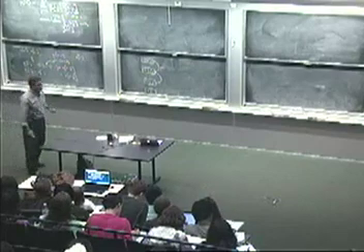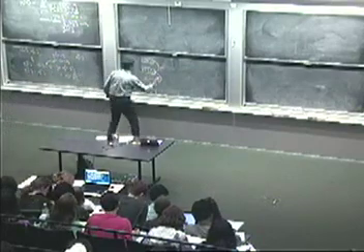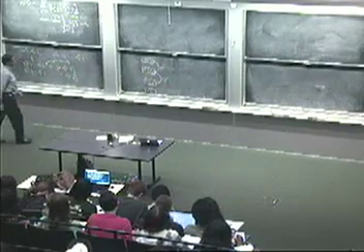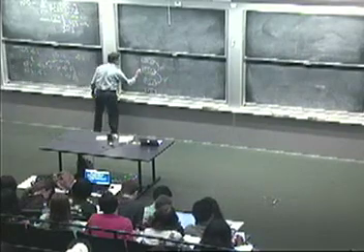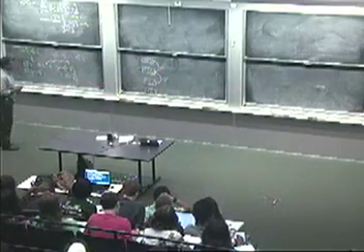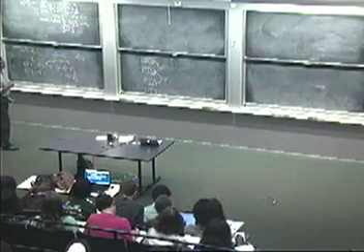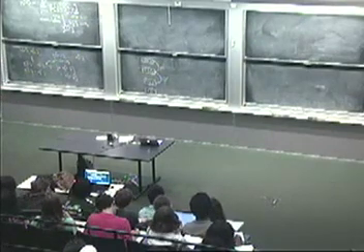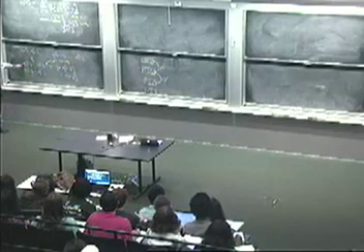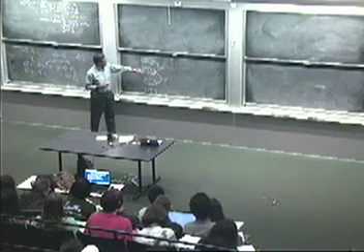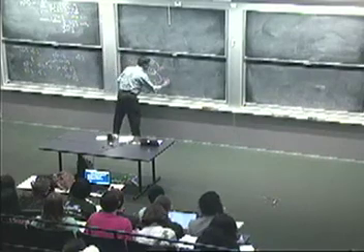Okay. And then I guess you've got to go back to this to think about what's happening. So I'll allow you to think of a 0 sitting at the input here. So what would the parity bits be? The first parity bit will be the exclusive OR of the 0, 1, and 0, so it's going to give you a 1.